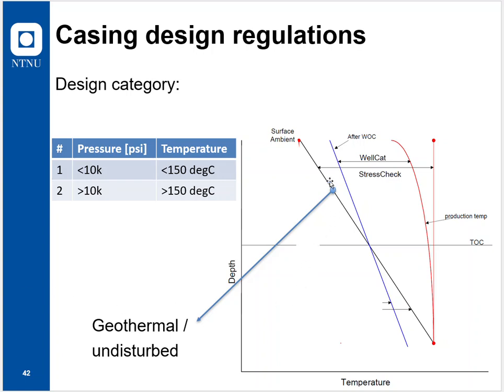You see, in the standard calculations, typically you'll find that a software like StressCheck from Landmark doesn't model the temperature. We see the curved red graph is the temperature modeled in the producing well, using the geothermal gradient, and it will tell you this is the temperature in either the tubing or casing that you're doing the design analysis for.